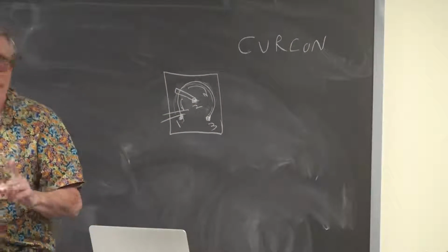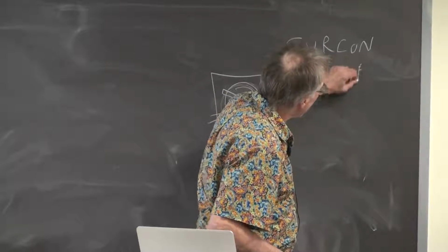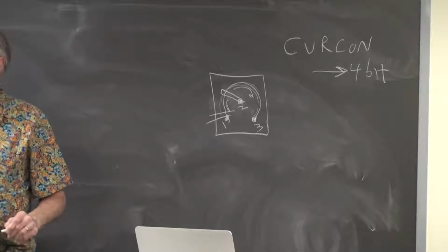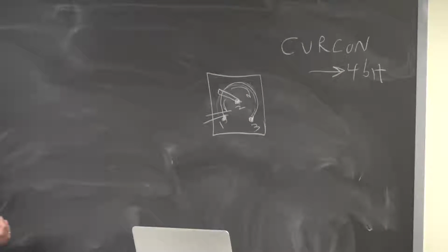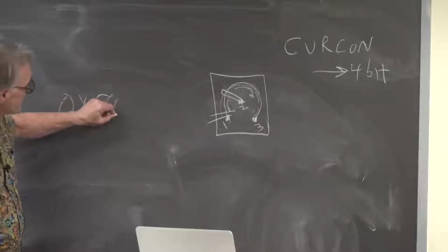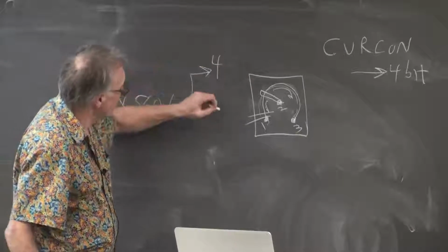The reason for that is that you cannot blast just the 4 bits out, but rather you have to send the setup bits along with your 4-bit value. You remember that the setup values were 8060, where these 4 bits are the voltage.